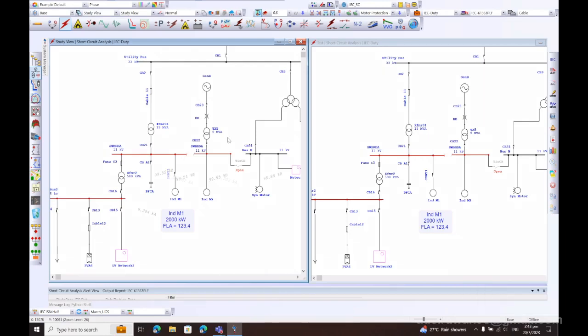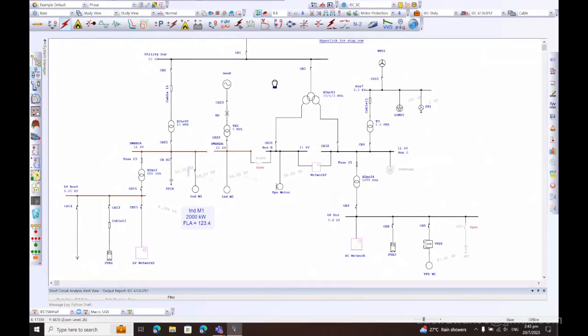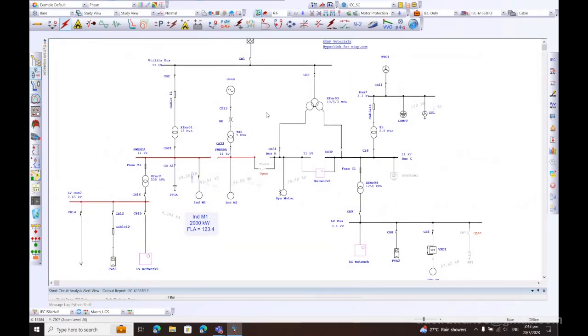Thank you, Ganesh. Okay, let me quickly move on to different modules. So these are basically for the short circuit calculations, you can actually run a duty calculation. The duty calculation basically helps us to identify, or makes some comparison with your equipment selection. If the calculated value goes beyond your selection, it flags it out.